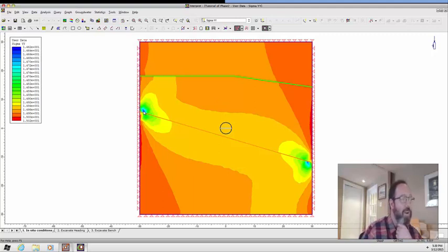And you can see that although there's a lot of color changes, basically it's more or less saying it's 15 MPa everywhere. Although clearly there's something going on with this joint, and that's because of the boundary effects from the end conditions that we decided to use for this joint, and they're obviously having some small minor effect. But the important part is that the vertical stresses are 15 MPa, and that's what we wanted them to be. That's what we entered, and you always check to make sure that the model has executed and provided results that are exactly consistent with the way that you set them up.